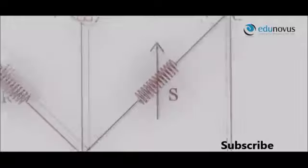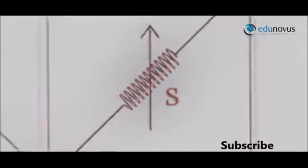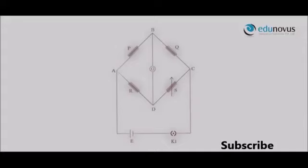Now, adjust the variable resistance S until the deflection in the galvanometer becomes null. When there is no current through the galvanometer, the bridge is said to be balanced. That is, the voltage difference between points B and D is 0. At this condition, the current flowing through the resistances P and Q is I1, and the current flowing through the unknown resistance R and through resistance S is I2. As we said earlier, the points B and D are at the same potential.